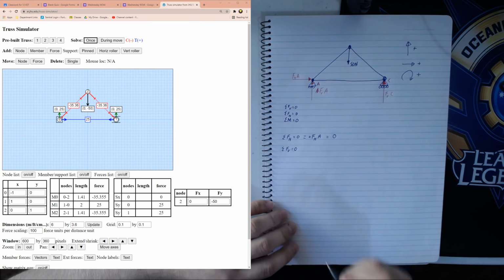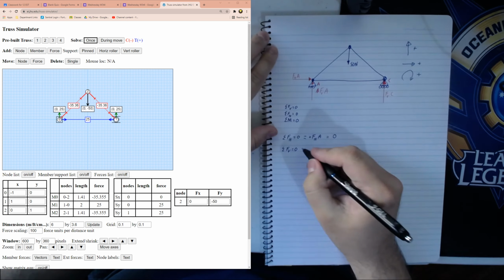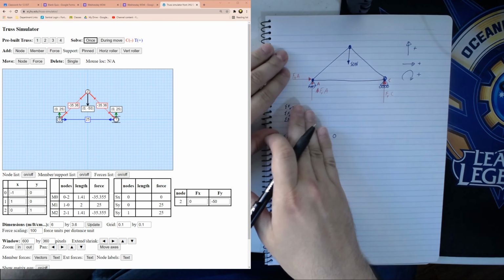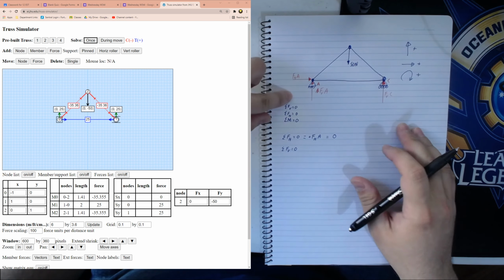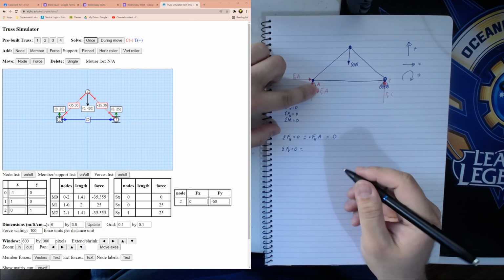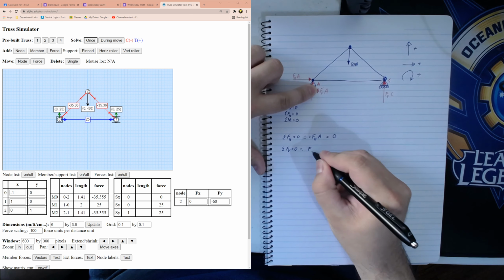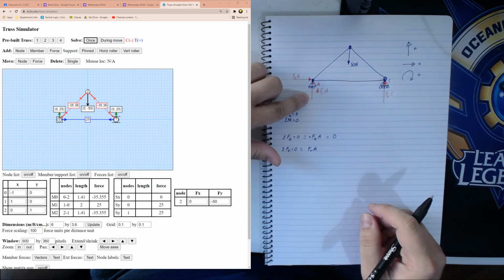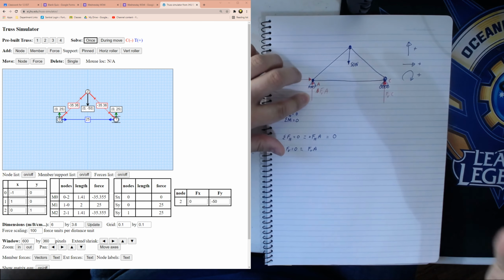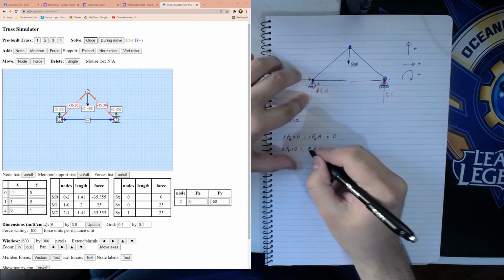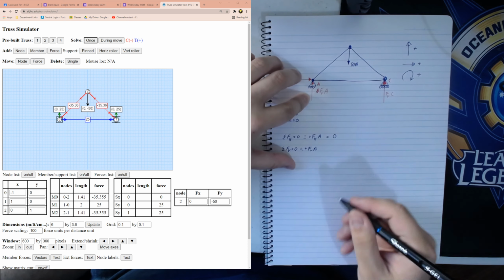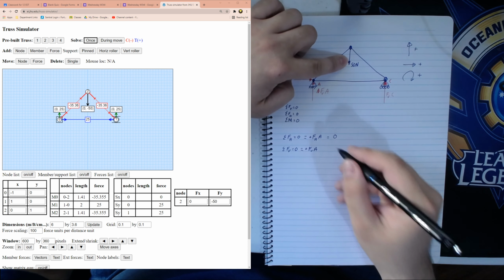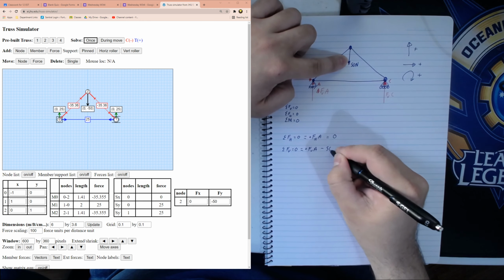So now let's talk about something a bit more difficult, where we have our sum of all forces vertical equals 0. So let's get all our vertical forces. And just for the simplicity of this video and explaining to you, let's go from left to right. Let's start over here. Our first is this one, which is our force VA. And in our example over here, we said up. So we're going to assume that we're correct, and we'll say positive. So plus force VA. Then our next force is this one over here, our 50 newtons. So we'll say minus 50 newtons.